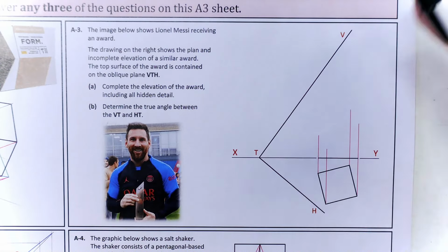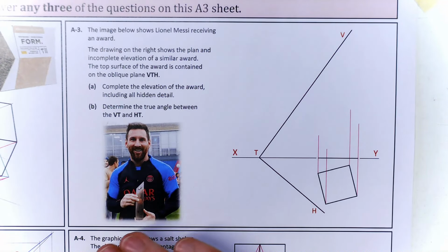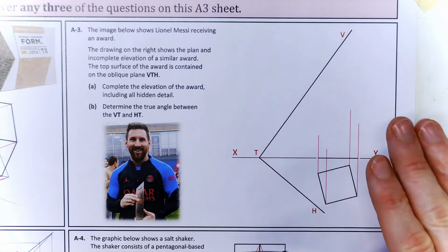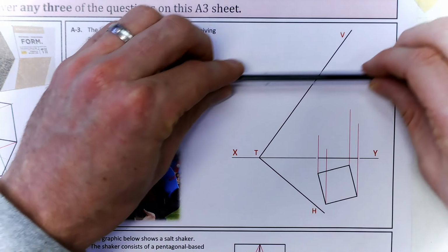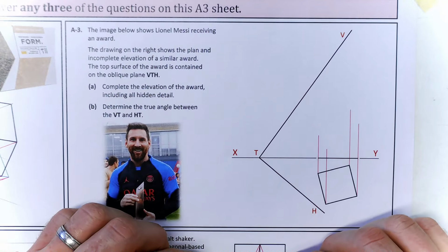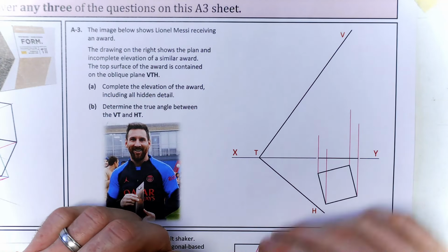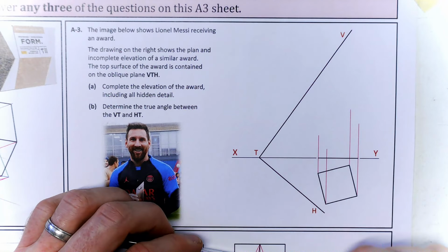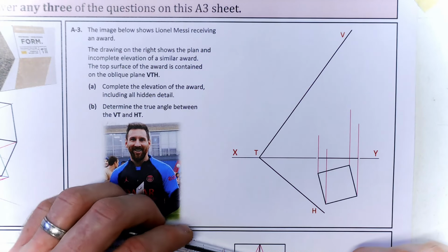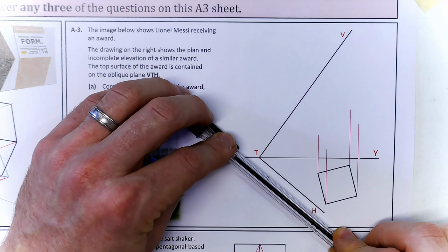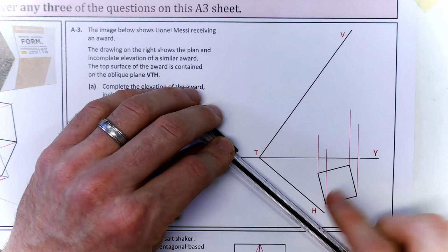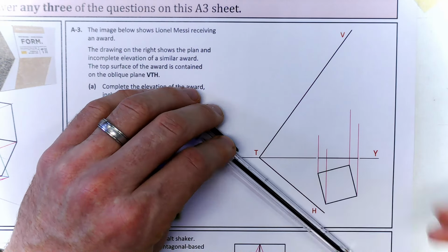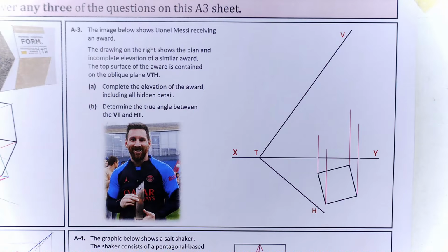So on this plane, we're going to take horizontal sections through the plane, and that's going to result in horizontal lines on the plane, and that will give us the heights that we need. A horizontal section on this plane results in lines that are parallel to the HT, because the HT is a horizontal line also. And we know that parallel lines are parallel in all orthographic views. So that's the principle that we're trying to apply.